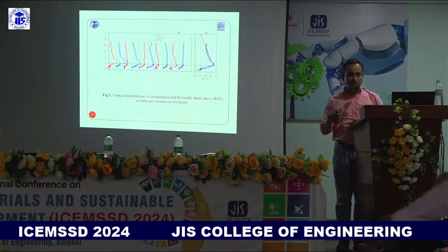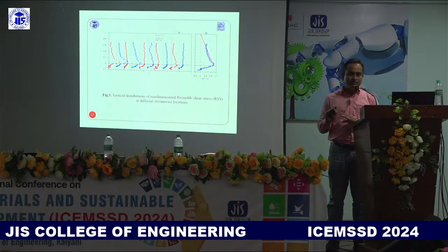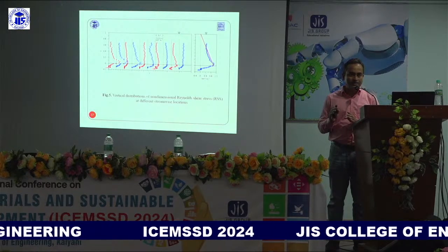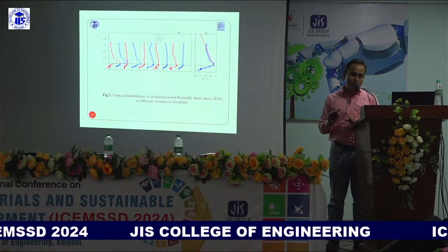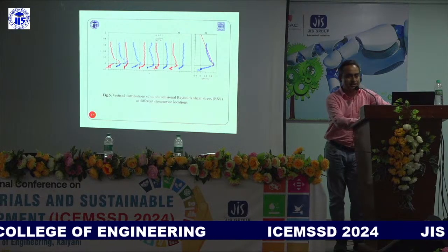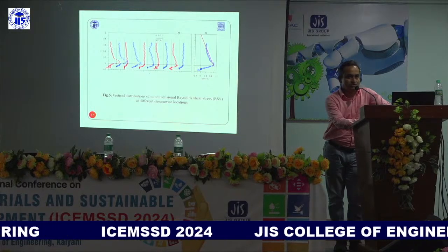Bed means actually the bottommost layer of the river, and if we make any artificial arrangement of the river in a channel, then the bottommost line of the channel is called the river bed. So here at the bed, as there is no velocity, we get the Reynolds shear stress as 0.